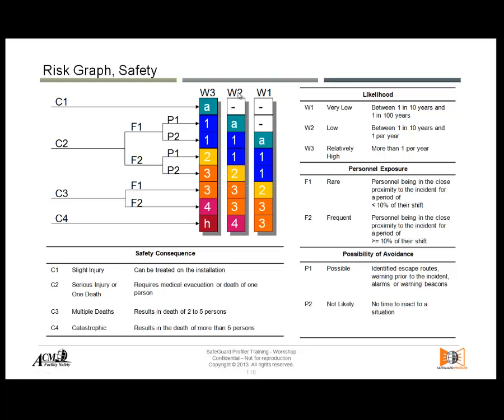Again, we're supposed to have the HACCP analysis done before we start doing this methodology, just the same way as for LOPA, layer of protection analysis. We need the HACCP to have identified all the hazards, and then from those hazards we picked the ones that are complex or that have high risk, or another criteria chosen by the company.